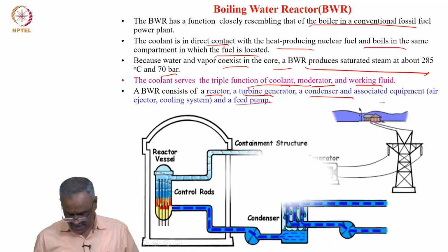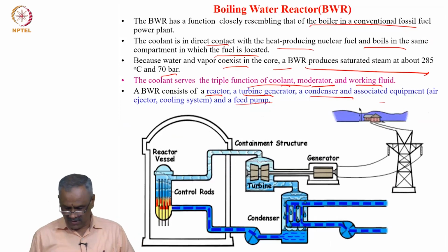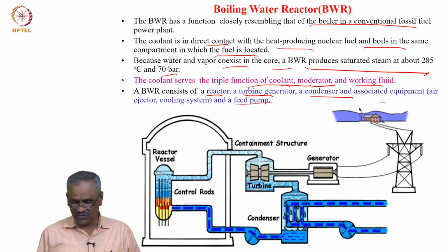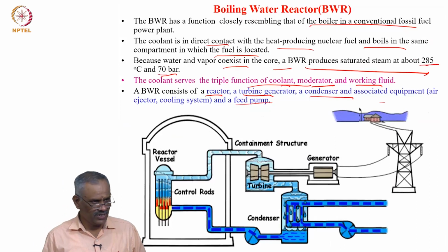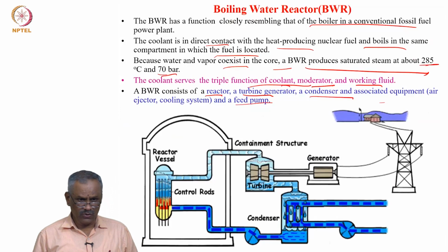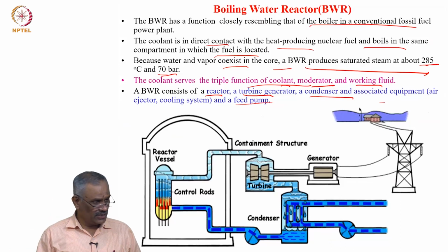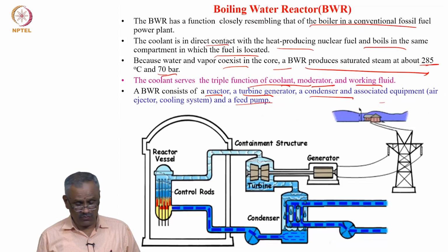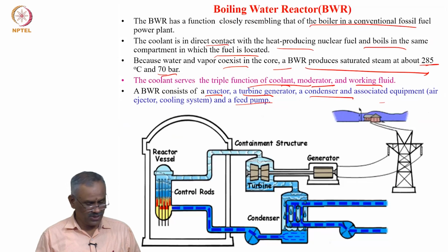If you look at that, it is simple compared to the other one, but the only thing is you get low pressure and low temperature here, 70 bar and saturated temperature. You know that in a once-through supercritical pressure boiler you have both, and in general fossil fuel based power plants you have 3 components, including a superheater, but this does not have a superheater.